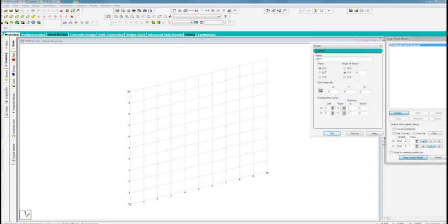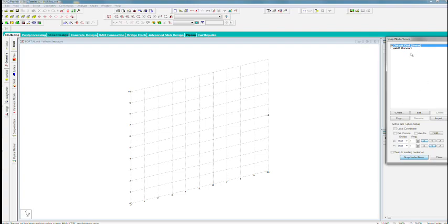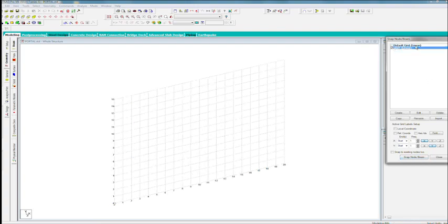We need grids to make them even every foot. Let's make it 20 to the right. Remember the spacing, and then we'll make it 15 high, so we'll be right on the outside. And so this is good, and we'll say OK, and that'll create our grid number 1. Check the box, Grid 1 becomes active, and there we are. Our 20 feet across here and 15 feet. So now we can just begin to snap our members into the location where they go.